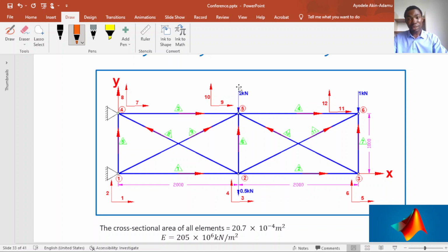I've already explained what I'm explaining now in my previous video, but I'm doing the explanation again. To define a finite element model for a truss system, first we need to number the elements. The elements can be numbered in any order of your choice. It depends on you. In this problem, I decided to number them this way. The numbers in the triangles represent my member numbers.